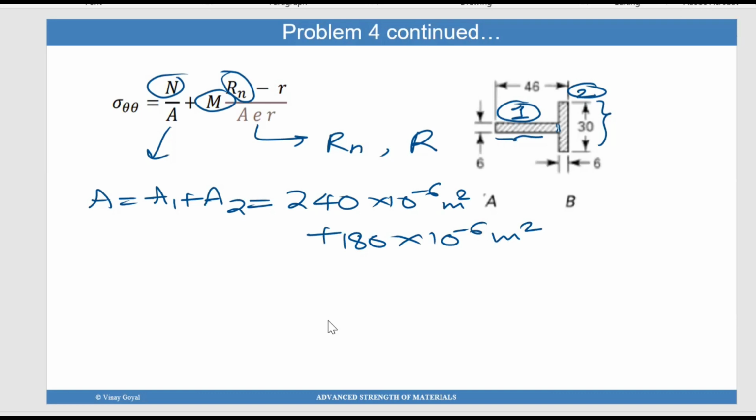So let's look at what the centroid of this thing is. If this is the cross section, say I define an axis something like this, like a centroid axis. So I say this is a Z centroid axis. I know what the centroid of the first rectangle is going to be. It's going to be at the center, so Z equals 20, and this z-axis goes through the very center of this.